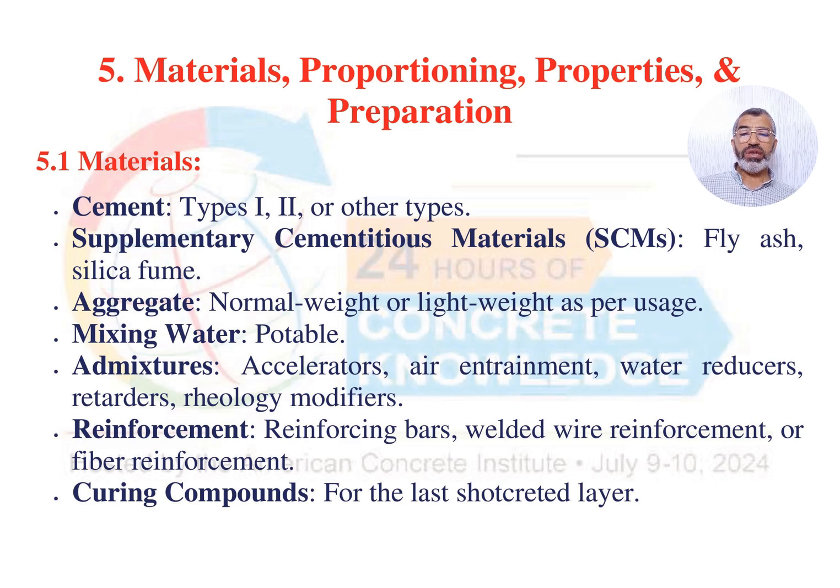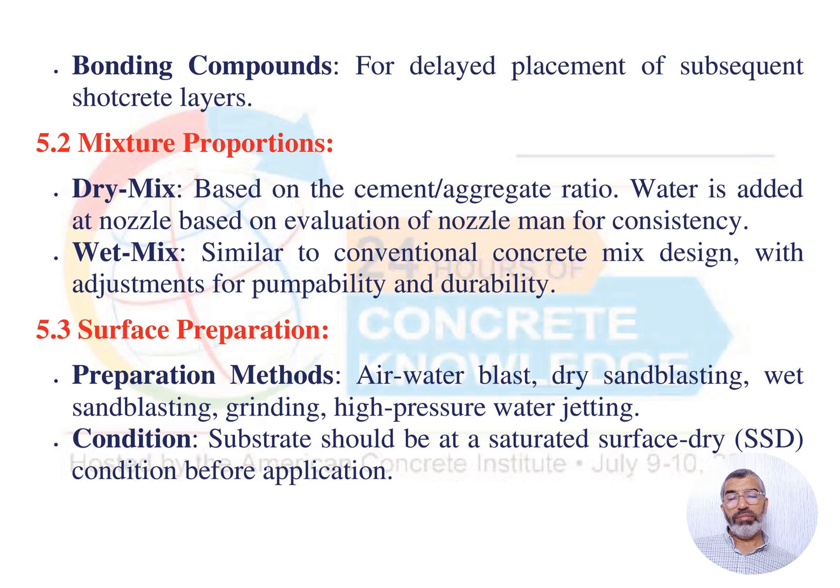Also, we may need curing compounds for the last shotcreted layer if we have a multi-layer thickness for the member to be constructed. Also, we may use some bonding compounds if we have some delay in time when placing subsequent shotcrete layers, to bond the successive concrete layer.